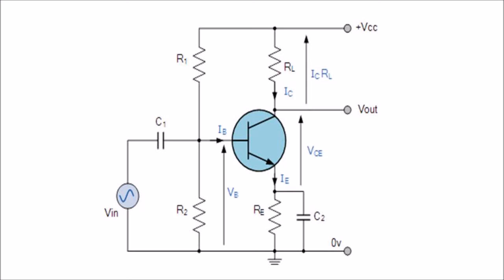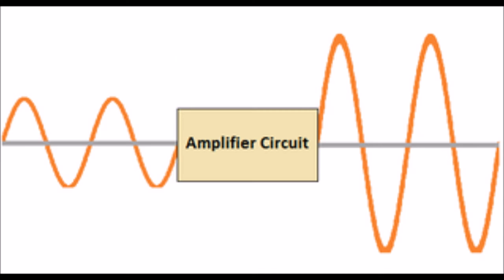The base of the transistor used in a common emitter amplifier is biased using two resistors as a potential divider network. This type of biasing arrangement is commonly used in the design of bipolar junction transistor amplifier circuits and greatly reduces the effect of varying beta by holding the base bias at a constant steady voltage. This type of biasing produces the greatest stability.